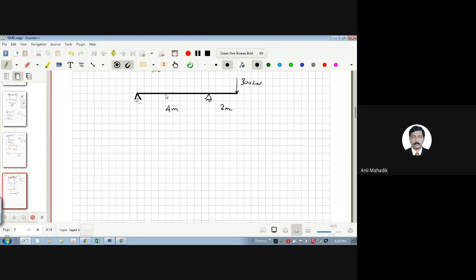Okay, there is no force here. So what will be the deflected shape as per your common sense? This will press it. Now let's say we have a platform or some wooden plank and you are standing here. They are anchored at this point, so they will not lift up due to the hinge connection. We are anchoring by bolt or something, and now you are pushing this downward. So what will happen? There will be downward deflection here, and because of that this will go upward.